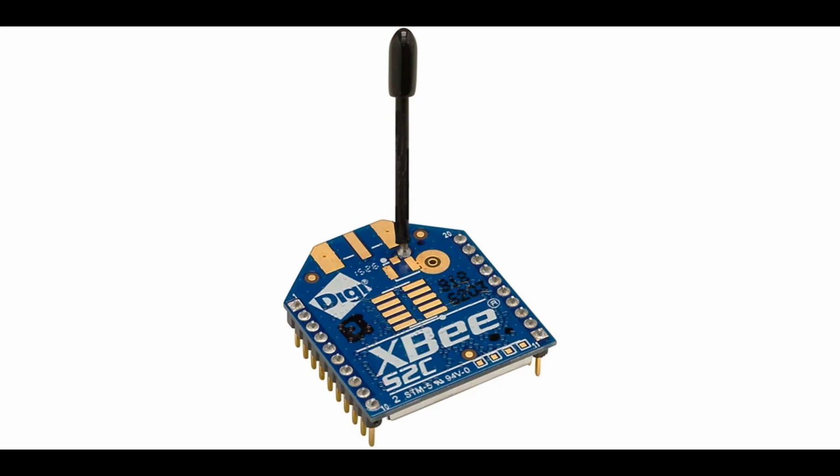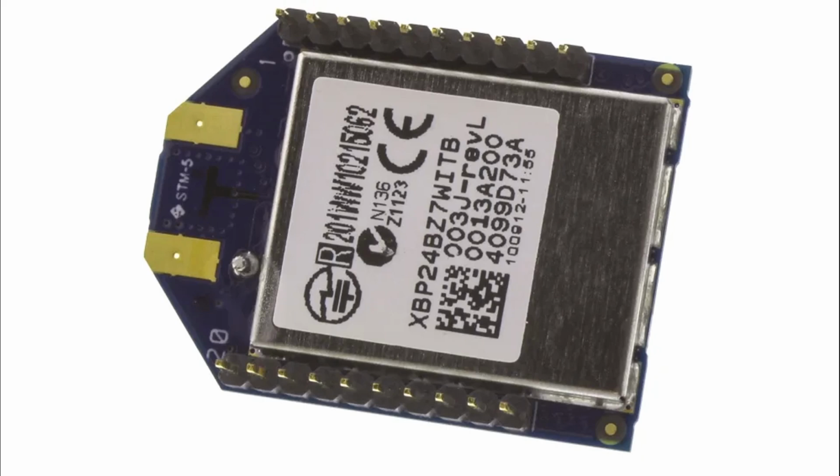5. Telegesis Zigbee modules. Models: ETRX357, ETRX3 series. Features: compact modules with options for external or built-in antennas. Easy to use AT command interface, simplifying integration with microcontrollers. Pre-certified Zigbee modules, saving time and regulatory compliance. Widely used in Europe for smart home and energy management solutions. Applications: smart metering, home automation, HVAC control, and healthcare applications.